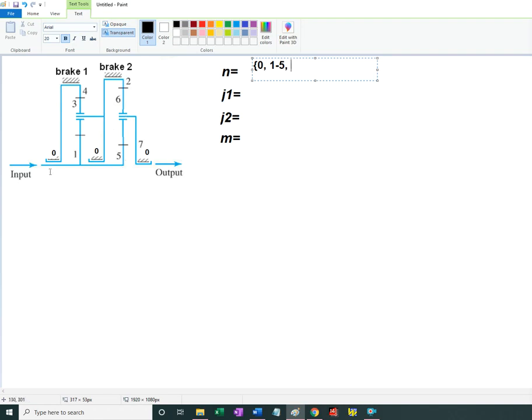As you can see, they are a single unit, single body. We then have number 2 as a separate body, and 3 as a separate body. 2 is the ring gear, which is also the carrier, the arm for unit 1.